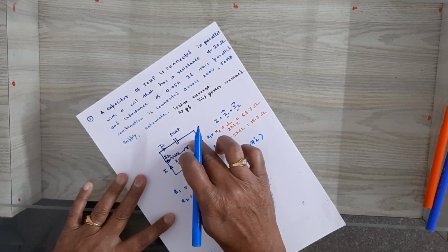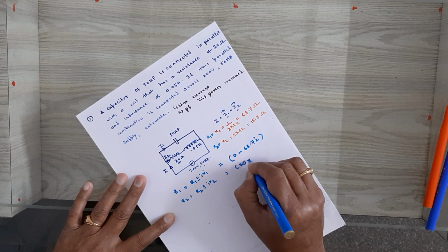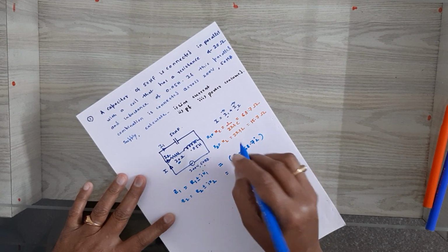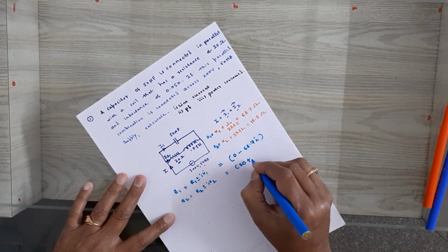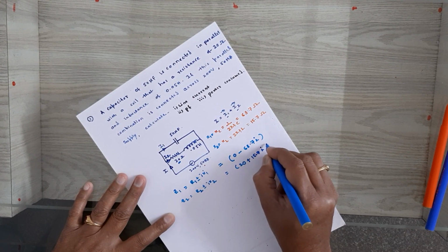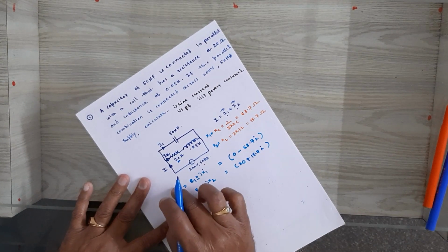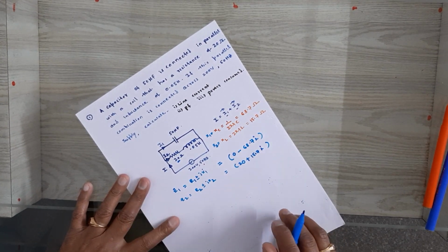What is the type of reactance? Inductive reactance. Therefore what you have to take? You have to take it as a positive. Then what is the value of X2 here? It is 15.7 I. Okay. This is how we have to represent Z1 and Z2.